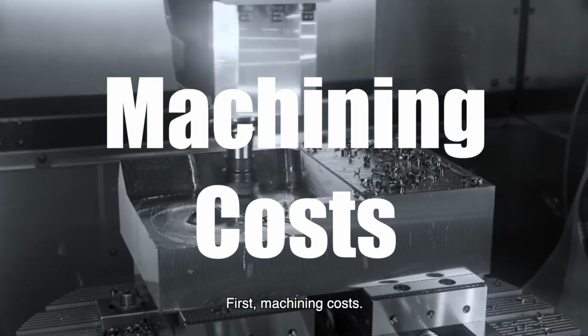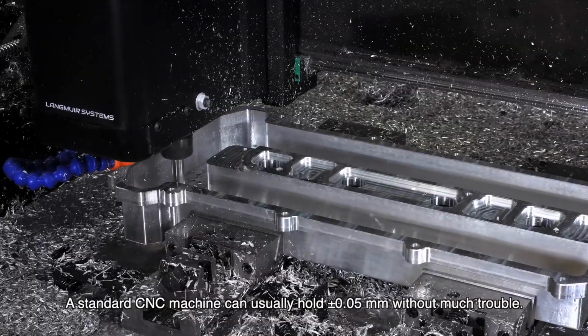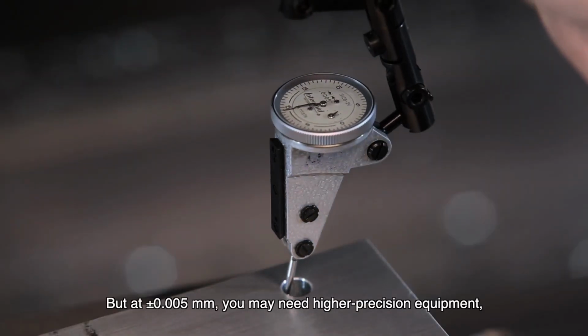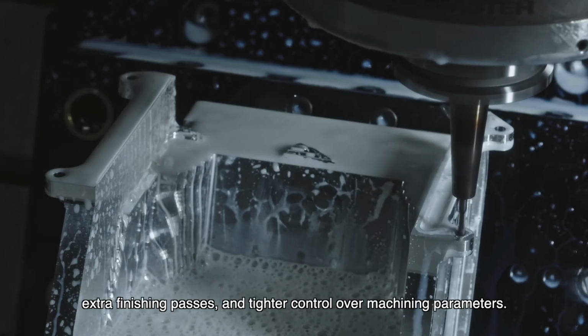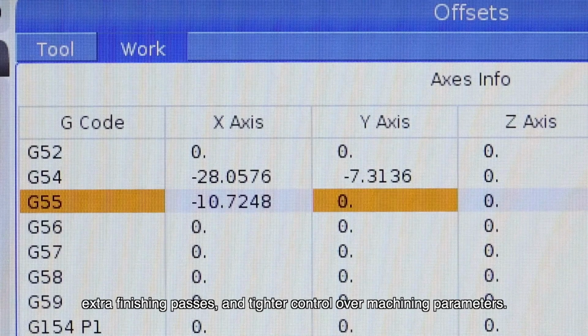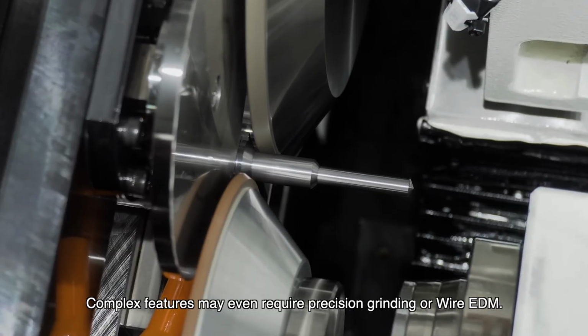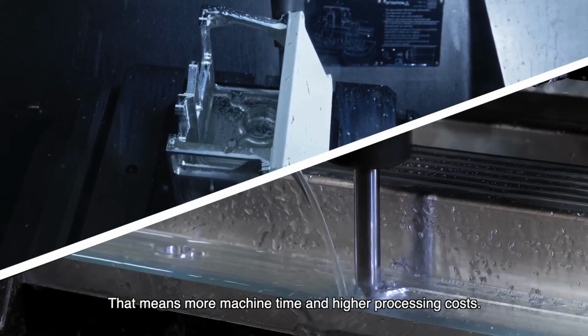First, machining costs. A standard CNC machine can usually hold plus or minus 0.05 millimeters without much trouble. But at plus or minus 0.005 millimeters, you may need higher precision equipment, extra finishing passes, and tighter control over machining parameters. Complex features may even require precision grinding or wire EDM. That means more machine time and higher processing costs.